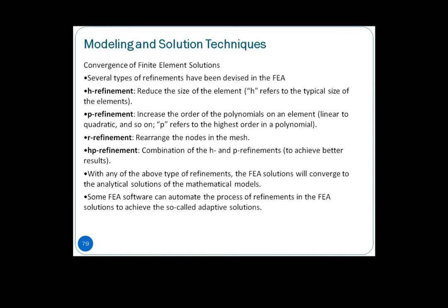That is what we call the mesh independency test, where you play around, same as adaptive. Adaptive automatically helps you reduce the size, then you find the suitable mesh that can converge and give you a relatively reliable result. So the mesh independency test is similar to adaptive meshing, but you have to do it manually.